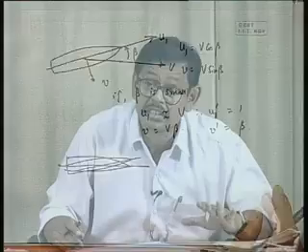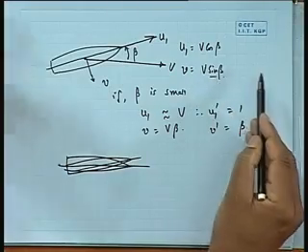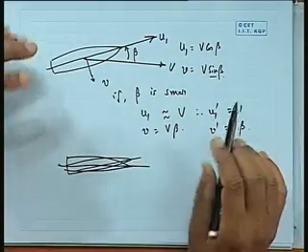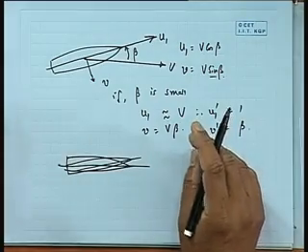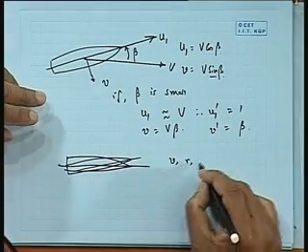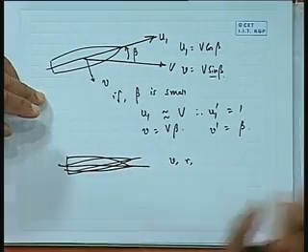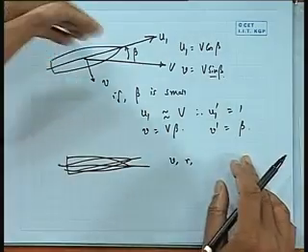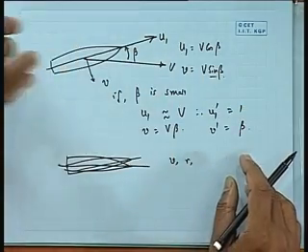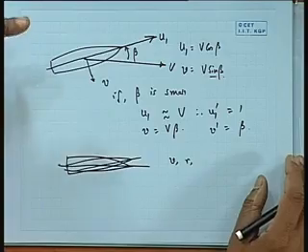See, these equations are linearized anyhow. The very word linearized equation implies that V dash is small, V is small. V small means that sin beta is small, means beta is small. So what I am trying to say is that this is very consistent. There is no ambiguity here, because we are looking at small values of V, small values of R, etc. It automatically means that beta is small. You cannot have large beta, because if it was large beta, you couldn't use this equation up to only first order. Then the Taylor expansion had to go to higher order. Anyhow, having said that, I hope this is kind of clear.